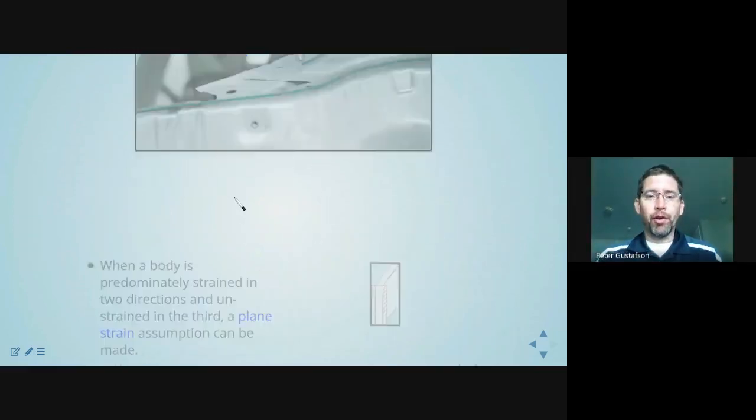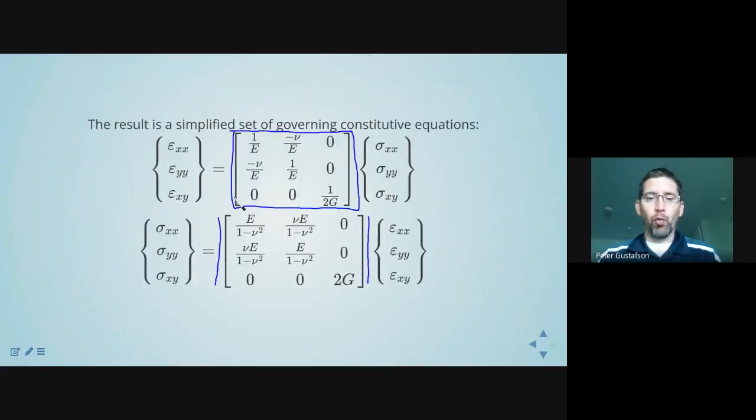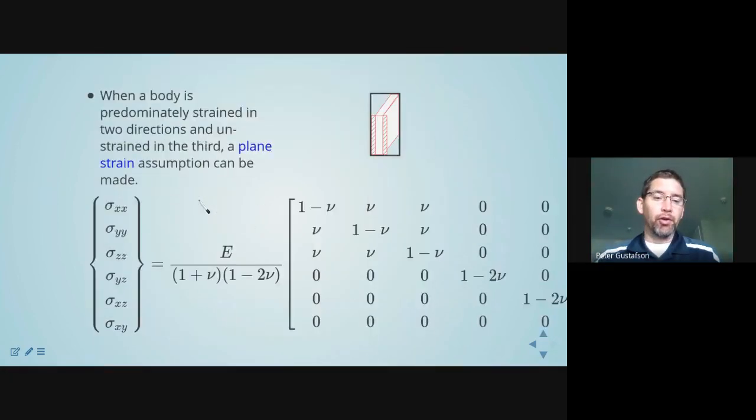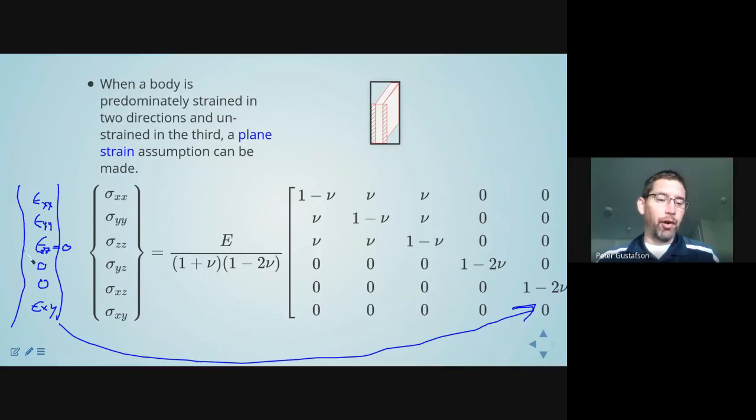Really, the better description is, it comes down to this. It's when it's reasonable to say the out-of-plane stresses are zero. If you can justify that assumption, then you can usually get away with plane stress. If, on the other hand, it's reasonable to assume that the strains are zero out of plane, then you use plane strain. So those statements are generally true most of the time for thick and thin materials, as Nicole's question asked, but not always. So use your judgment.